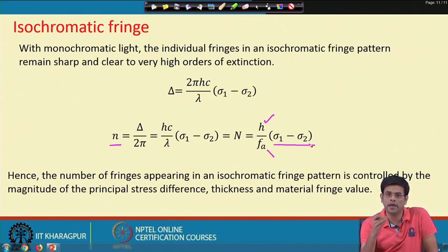Rather, we use a polymer kind of material on the surface of the crystalline body, and then try to find out the stress pattern along the surface of the material due to the application of load. So this procedure also helps show how the surface stress pattern will be in the case of a complicated body. Here this completes our discussion on photoelasticity for this course.